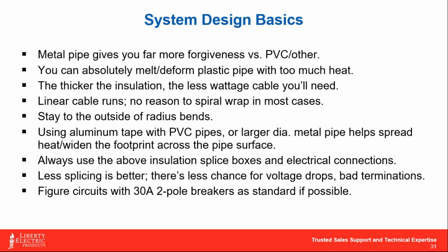So we want to proportionally spread those runs across the bottom half of the pipe. If you could imagine a clock face, and you've got a run at say 4 o'clock, 6 o'clock, and 8 o'clock, that's probably where you'd want to put those. And take some aluminum tape, cover them, and now you're spreading that heat across basically the whole lower half of the skin of that pipe, which is definitely going to help out the efficiency of your system there.